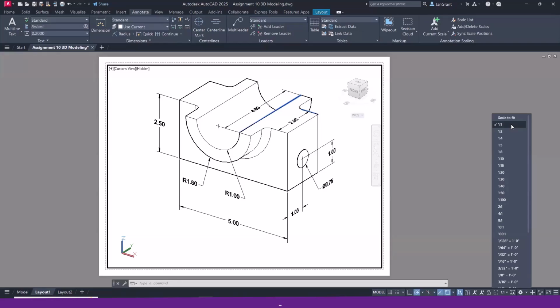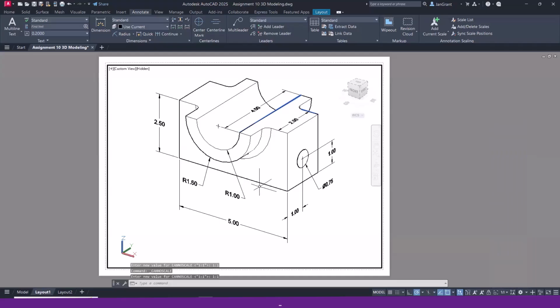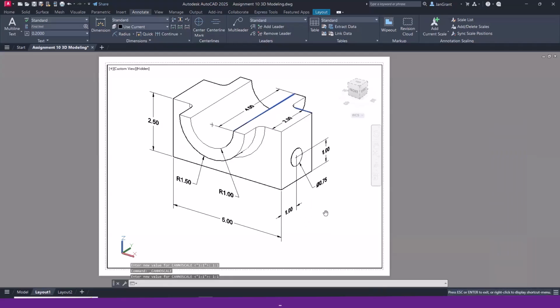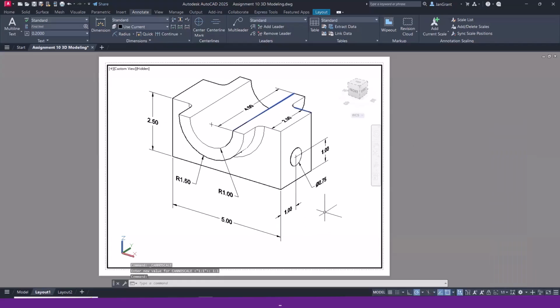In fact, you can actually lock it. There's a little lock icon down there too. But once you set the scale, you can pan, but you can't zoom or else you'll get out of scale. So I've got the scale set. I can put this drawing where I want to put it. Now, this is the important part. I want to double click out in the paper.